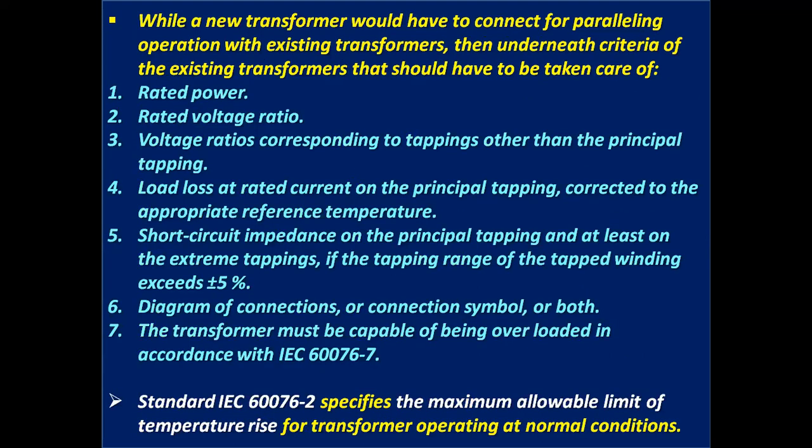While new transformers are to be connected for paralleling operation with existing transformers, the underneath criteria of the existing transformers should be taken care of. One, rated power. Number two, rated voltage and rated voltage ratio. Number three, voltage ratios corresponding to tappings other than the principal tapping. Number four,